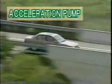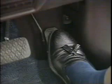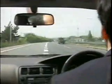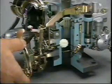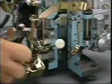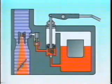Now let's take a look at the acceleration pump. We all know that to achieve quick acceleration, the driver needs to depress the accelerator pedal suddenly. The acceleration circuit is designed to prevent engine hesitation during such sudden acceleration. With the pump-type acceleration circuit, when the throttle valve is suddenly opened, the pump lever depresses the pump plunger. This increases the flow of fuel from the acceleration pump jet.